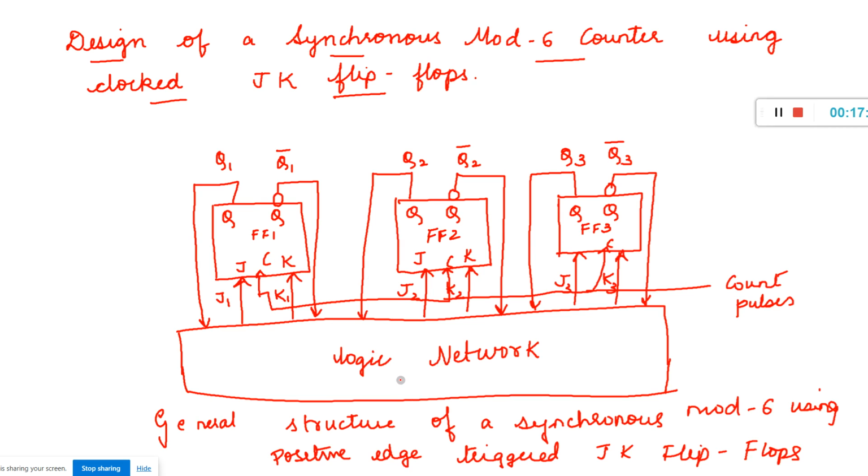This design we need to do by constructing the application table, excitation table, state table. Okay, so how do we construct those? Okay, we can see here. And one more thing, this is a synchronous mod counter. Why synchronous? You can see the clock. The clock is connected synchronously, at a time it is applied to the flip-flops.